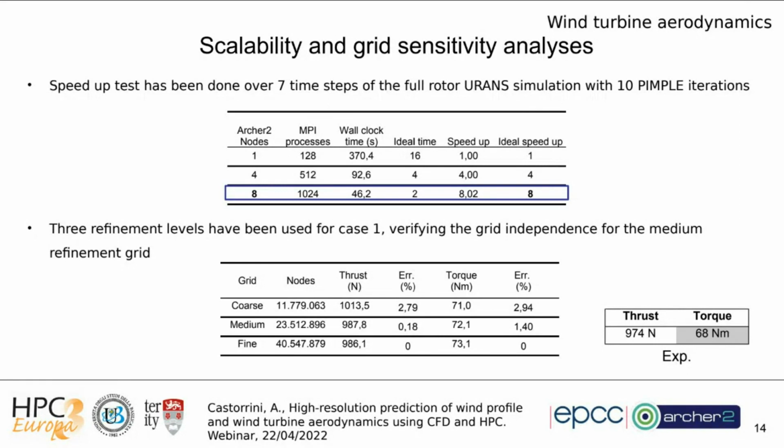We also checked the sensitivity of the solution to the grid and tried to get a solution from a coarse, medium, and fine refinement level of the grid.